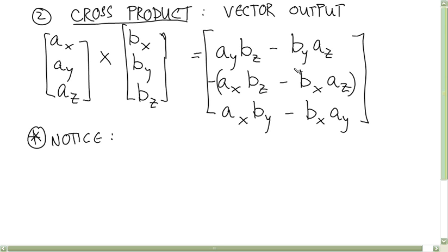And that's why when you do 2D moment problems, 2D rotational problems, you calculate the moment as a cross product, and that's why your moments always act only in the z direction. And that's why you sort of forget that they're even vectors at all, because you can just sort of treat them as numbers.